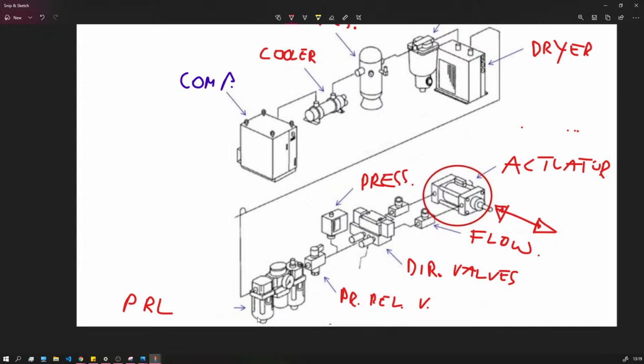Having filtered the air, we also want to set a certain pressure for the machine. So we have a pressure regulator in this block usually that sets the right pressure. That means the right force for our actuators. And let's say, modern machines don't have that lubricator, but some do.